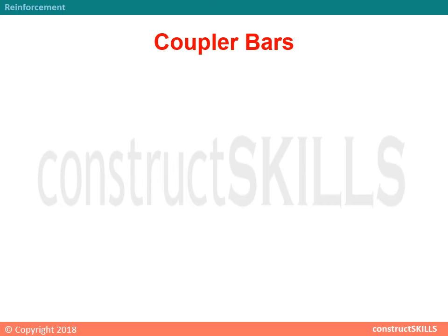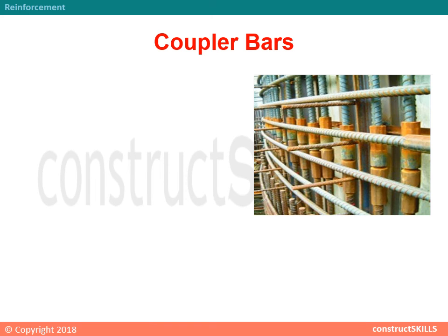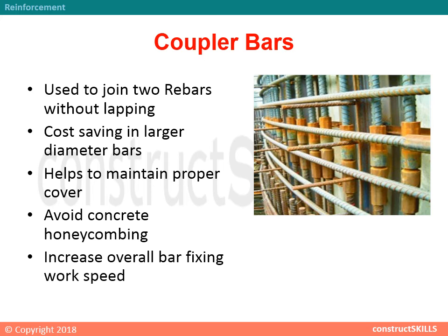Couplers of bars. It is used in different ways. It is used to join two rebars without lapping. It is cost-saving in larger diameter bars. It helps to maintain proper cover. It avoids concrete honeycombing, and also increases overall bar fixing work speed.